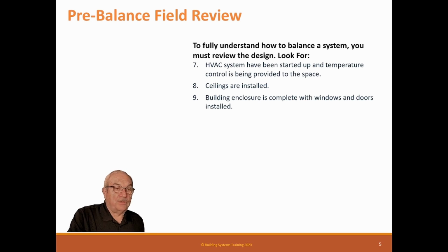It sounds weird, but we've had general contractors try to get us into balanced buildings that don't have any windows. We just can't do it. Well, you could go in and balance maybe some grills, but you should not, because you're going to have to remobilize to finish it once they do. And mobilization will kill you on productivity. So you need to say, no, when you're done, we will come and do the job.